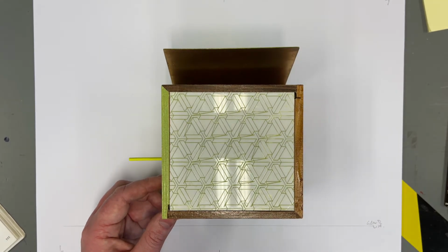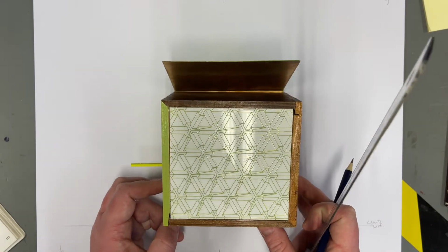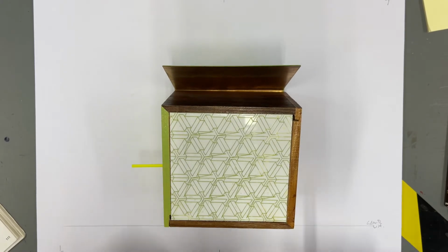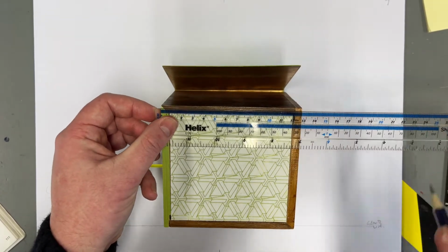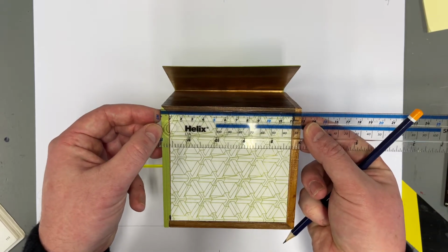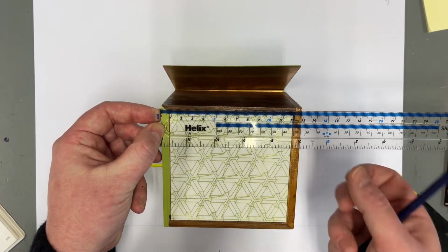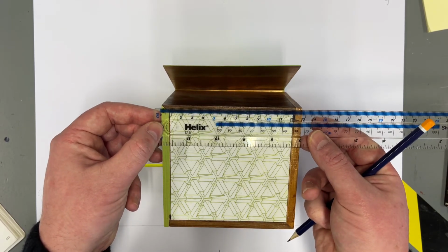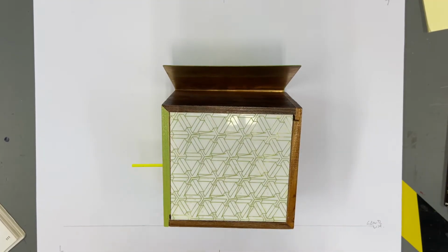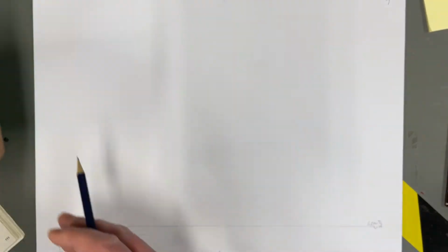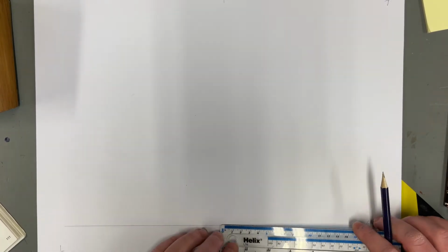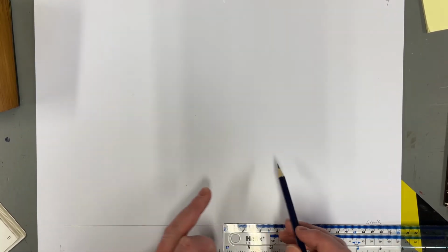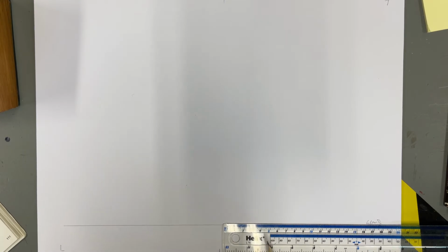Right, now I'm going to draw this at half size, that's 1:1 scale. Don't worry too much about my measurements because your designs will all be different. So I'm going to look at the length of the product, and we'll call this the front, the elevation, and let's say roughly about 128, 130, something like that. So we'll plop it over to the side just now, and down here we're going to place the elevation this time and project the end elevation over to the left instead of over to the right. Remember, you could do that both ways.